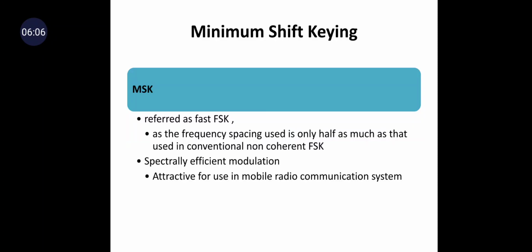So MSK is also referred to as fast FSK, as the frequency spacing used is only half as much as that used in conventional non-coherent FSK. An important feature of MSK is that it is a spectrally efficient modulation method. So it is used in mobile radio communication systems.